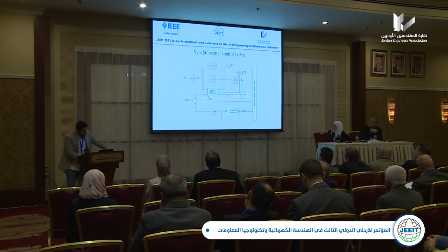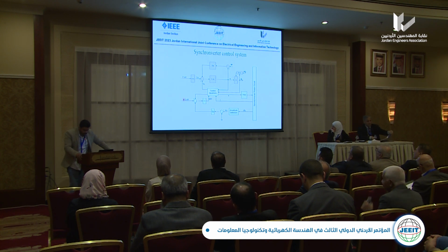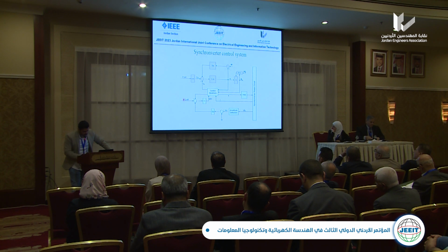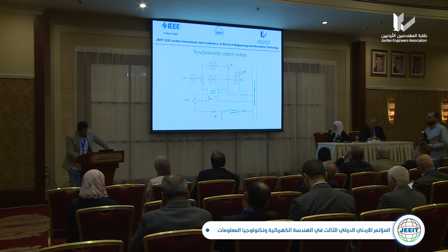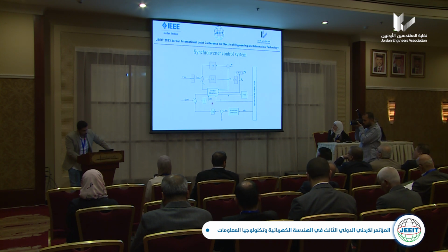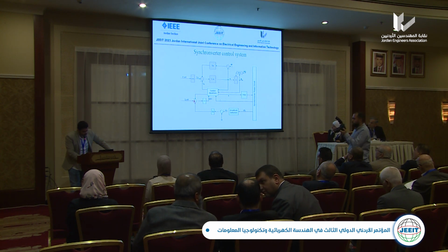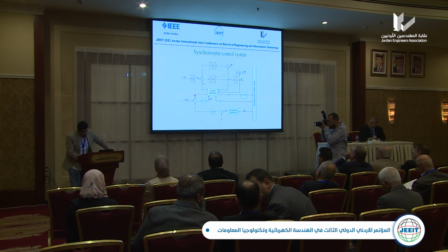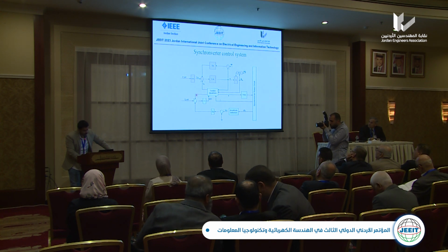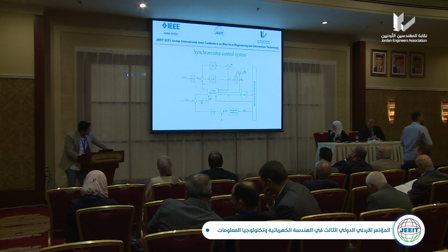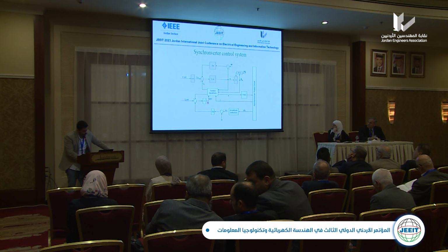Now we will go to the lower control loop, which is the reactive power control loop and voltage droop control loop. We have Q set as a reference point, which enters the summation point, in addition to dQ, which is the voltage droop control parameter. Then the real Q is subtracted at the summation point, and the result is multiplied by the integrator 1 over Ks to give us MfIf that we will need in the control equations.